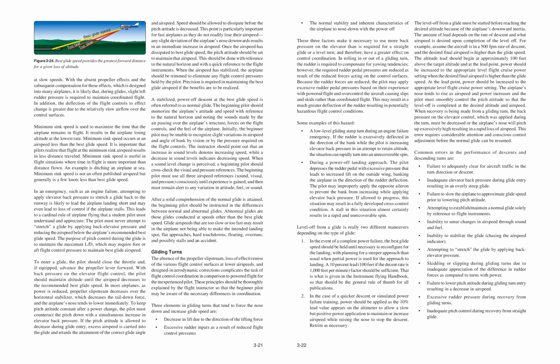The beginning pilot should memorize the airplane's attitude and speed with reference to the natural horizon, noting the sounds made by the air passing over the airplane's structure, forces on the flight controls, and the feel of the airplane. Initially, the beginner pilot may be unable to recognize slight variations in airspeed and angle of bank by vision or by the pressure required on the flight controls.